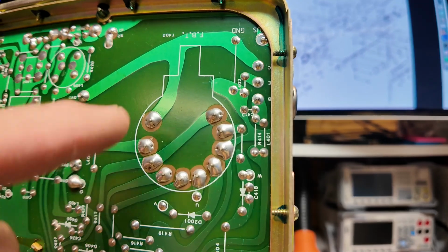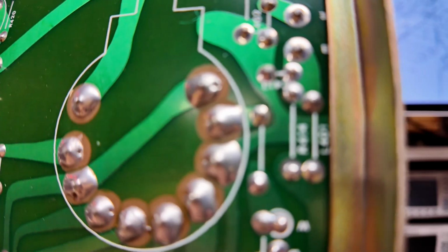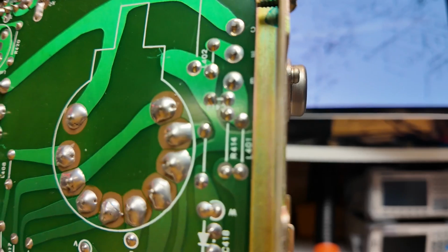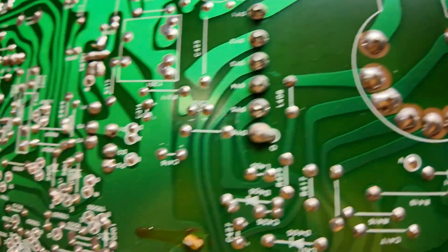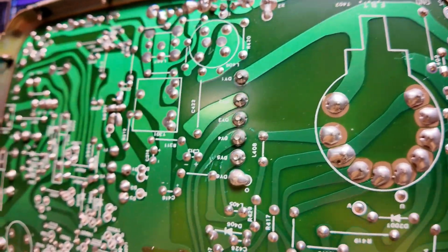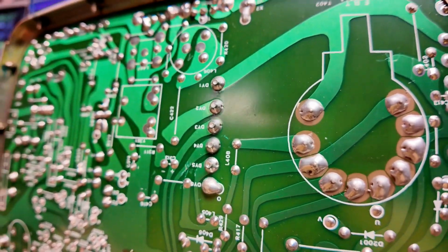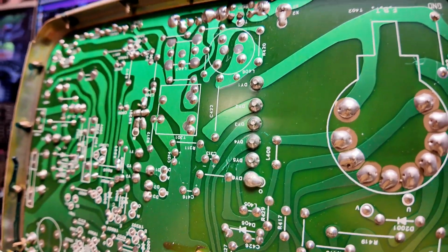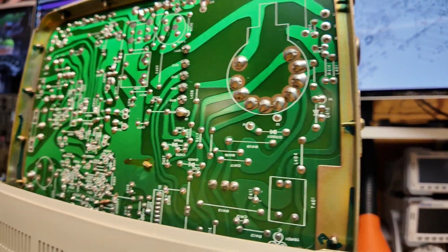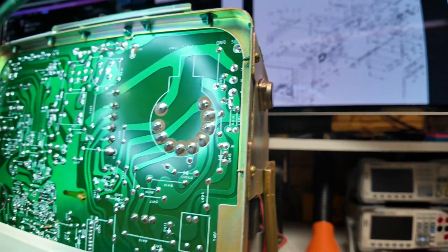Because these components are heavy, things like the flyback can end up with bad solder joints. Now, I don't know if that would affect vertical deflection. It's probably hard to see there. It's not in focus. There looks like there may be potentially some cracks in those solder joints. But it's always good to check any heavy connectors that are hitting the board, things that have wires hanging off of them, stuff like that, for any sort of damage from stress and things like such. I'm not seeing anything that looks too bad here. No, it really looks okay.